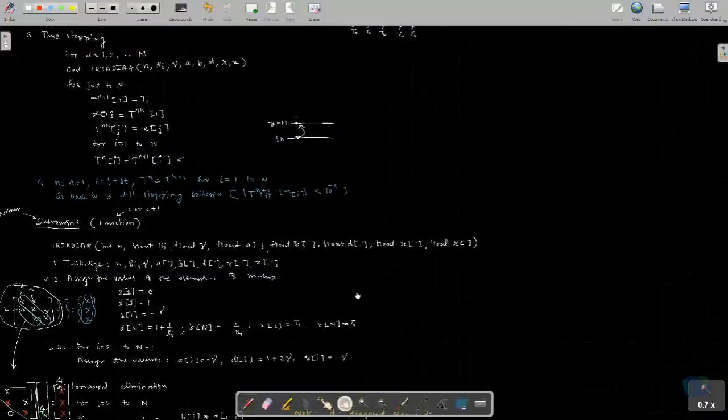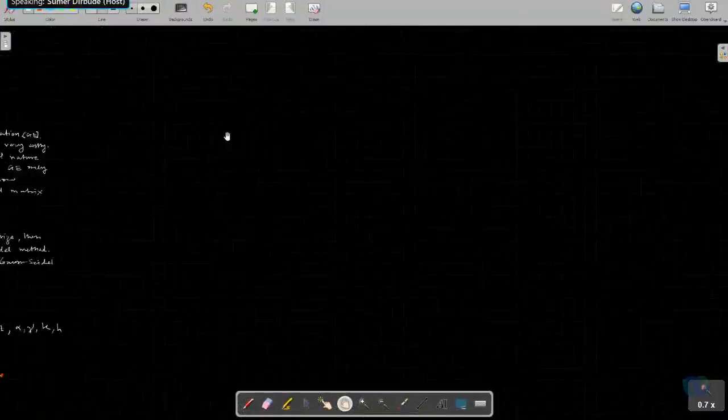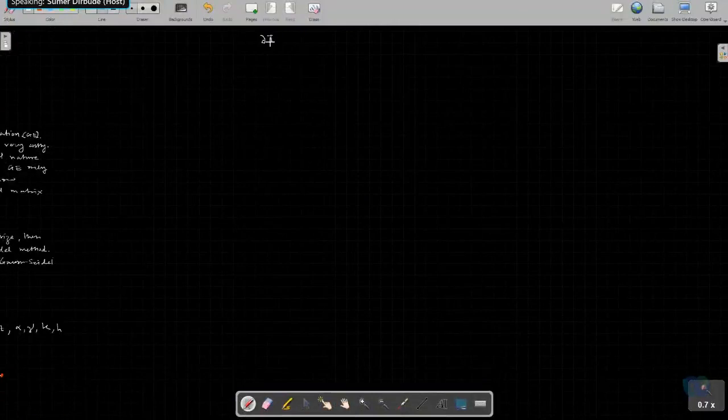Now I'll just make a general comment. What we have done is, for solving this type of problem, del t equals alpha del 2t del x2, we used one explicit method, and we also said that there are implicit methods.